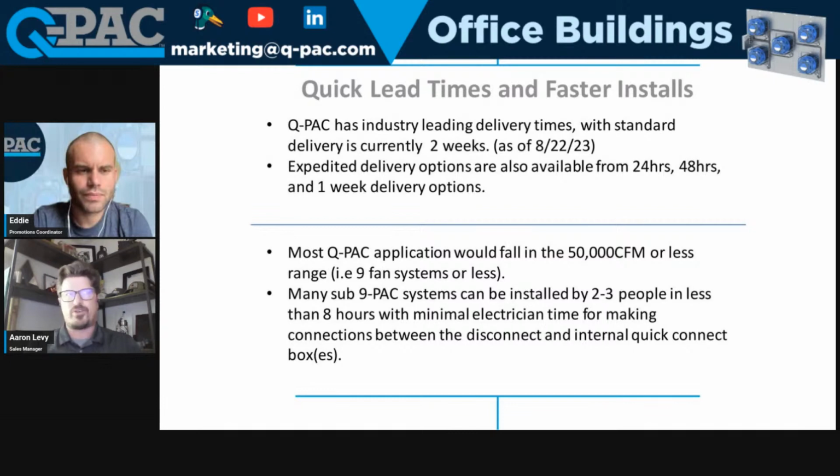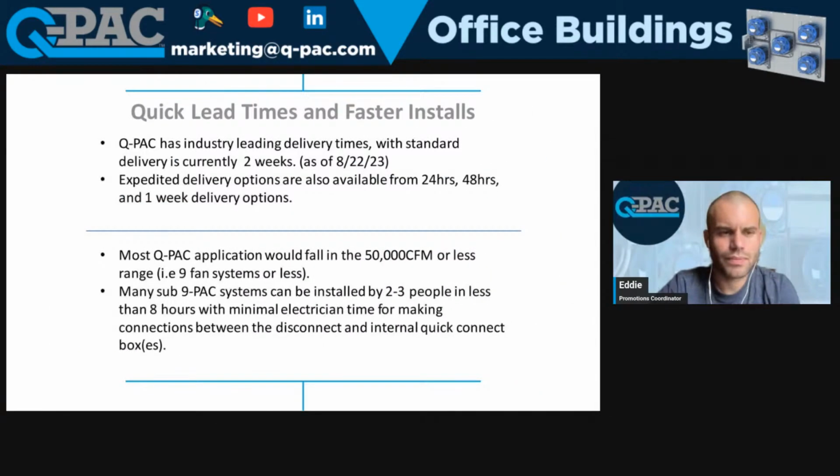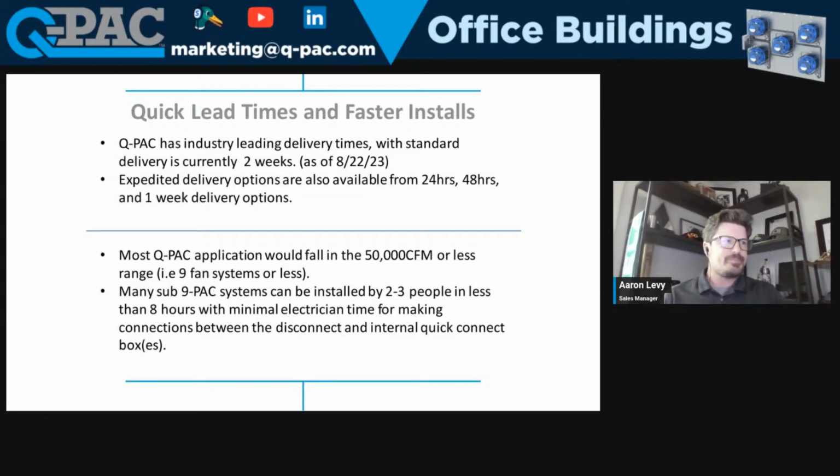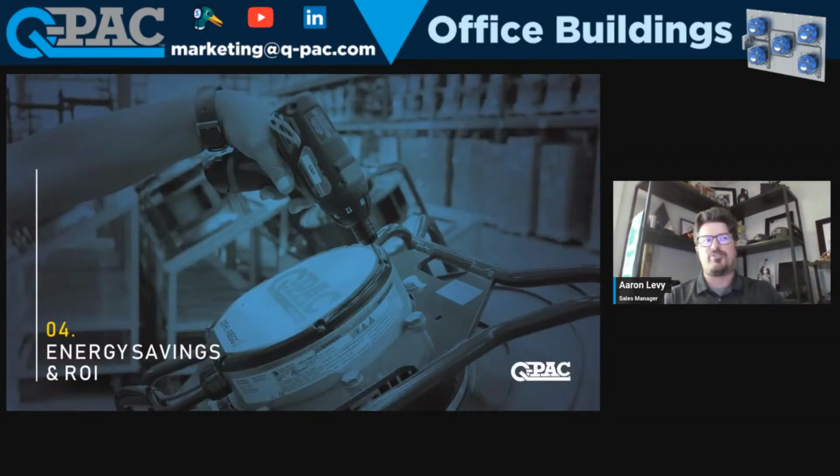As electronics and the winding process and everything gets better and better, we're now on third and fourth generation electronics from these manufacturers. So they've worked out all the woes of the first generation electronics, where people were just learning about ECs. These things have been around for almost 20 years now, if not more. That technology has improved drastically over that time, very much like VFDs did when they first came out compared to what they are now. So ECs don't tend to be as big of an issue as they used to be. It's just different technology that is becoming more and more of a standard.